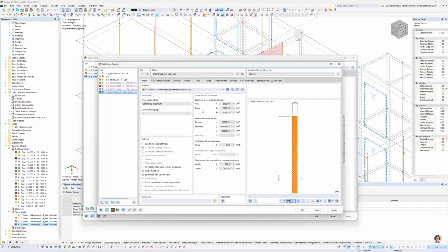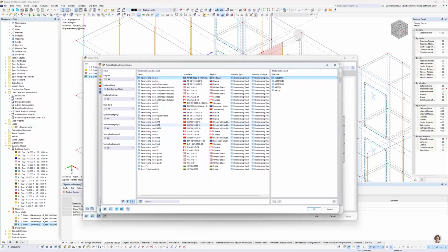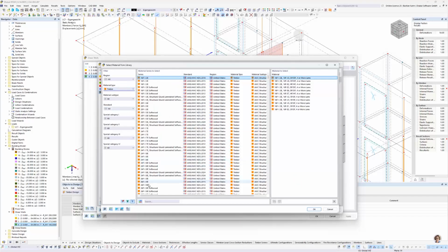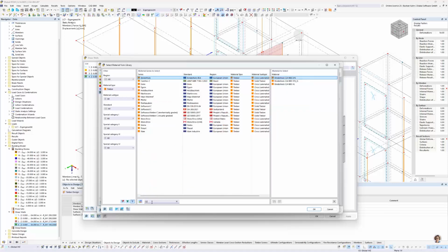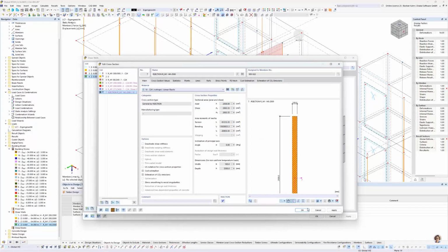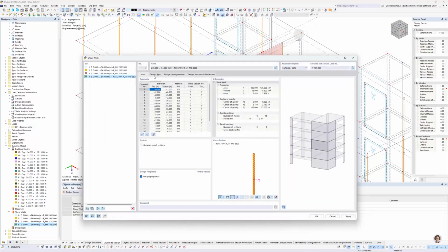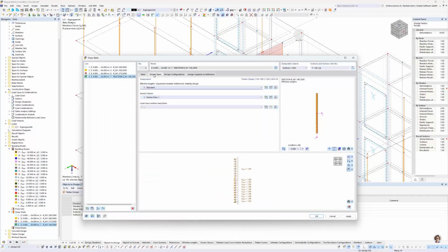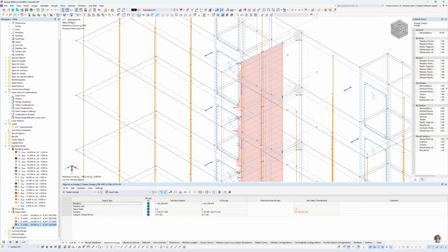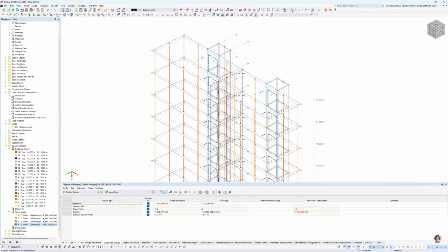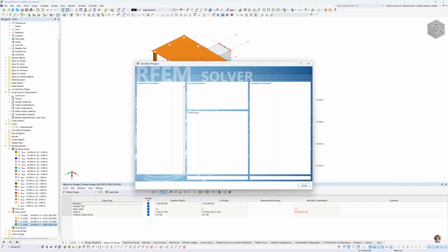And now, okay, one thing I forgot. I also have to define timber with C24 grade here, just as isotropic material, and press OK. And now I can do a buckling stability analysis together with the stress analysis from the add-on Timber Design in here. So that's quite a big benefit that the add-on Building Model can give you. It's not typically a software, it's just the add-on.